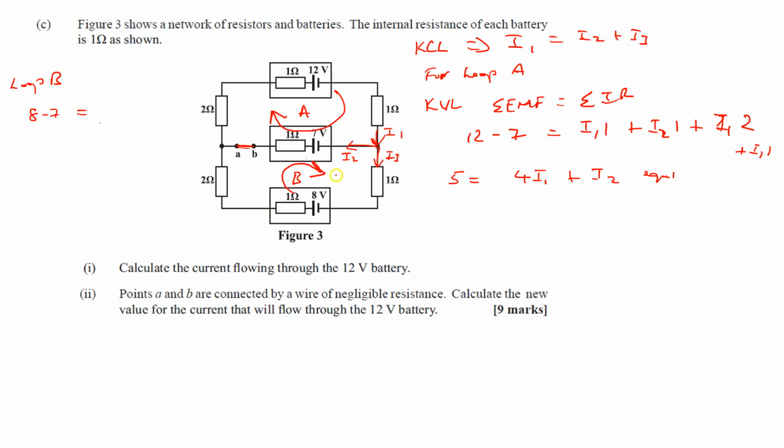We can start out with this one right here. All right. So we're starting out with the current coming. So I3 flowing through this 1 ohm resistor. So I have I3 times 1, which is the same thing as I3, plus. Then now I3 is the same thing that's going to flow through this internal resistance. So I have another I3 here, right?